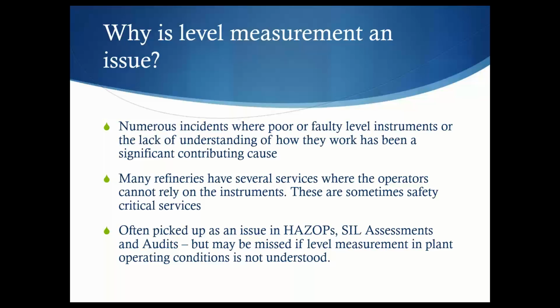So it's often picked up as an issue in HAZOPs, in assessments and audits, but it may be missed. And one of the things I find in HAZOPs in particular, people just assume that because the level protection is there and there's a trip, that it's going to work every time, or it's good for the service it's in, and they don't necessarily think about the type of conditions that could change that, which I'll explain as I go through.